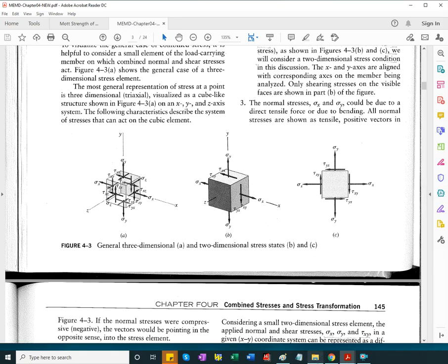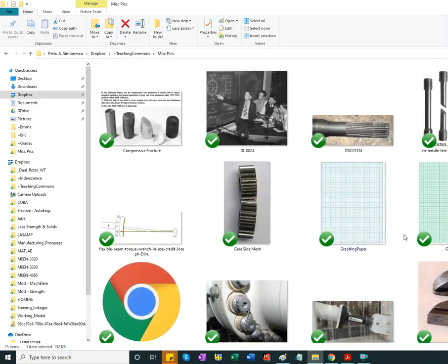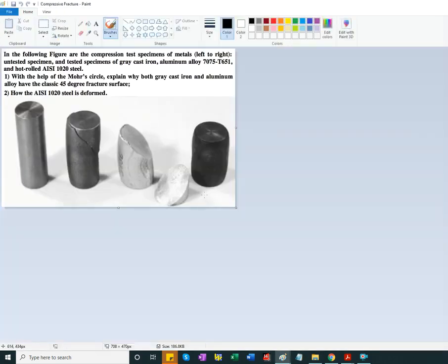And this kind of analysis makes sense, because we can have multiple situations. For example, different materials respond differently to stresses. So these two are brittle materials. This is how the original specimen looked in geometry. I cannot tell whether it's one of these three. So one, it's iron, aluminum, and this is a 1020 ductile low carbon steel.